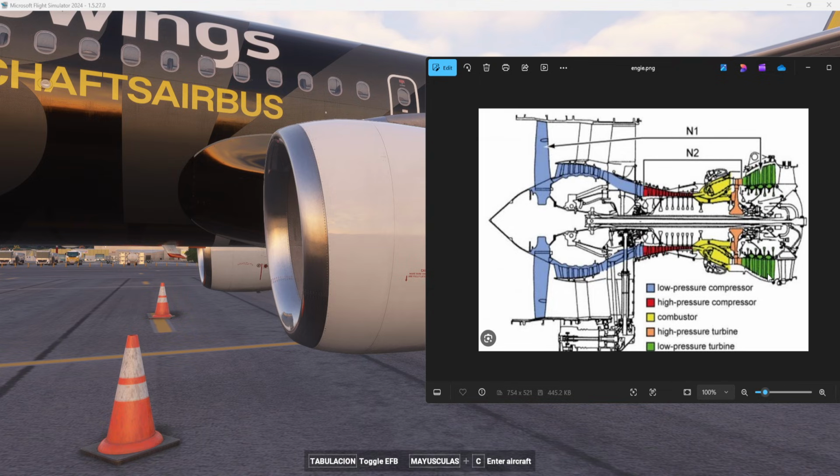Okay? It has a percentage. We are in aviation, we need to have a percentage, with sensors and equipment that send a percentage of the N1, and you as a pilot should only respect this percentage, which we are going to talk about later on. Then from the low pressure compressor, it now goes to the high pressure compressor. The high pressure compressor has 9 stages, so 9 rotors and 9 stators. Guys, I'm talking about the CFM56-5B, okay?